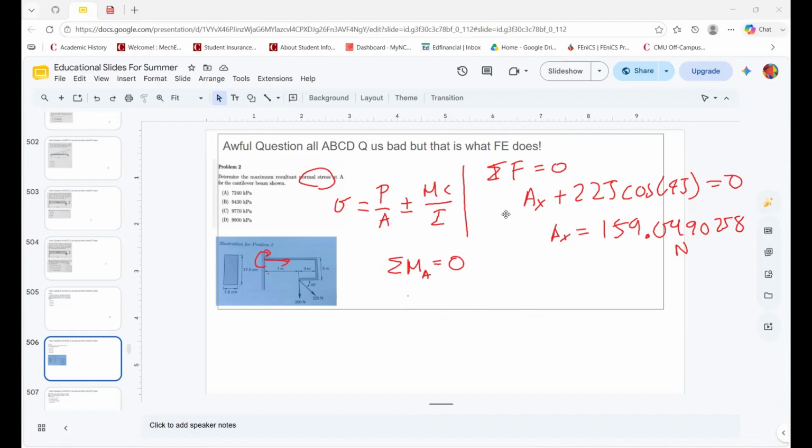The moment over here, we're going to do M at A, and we're going to choose a negative direction for it for now. And this was -2. Yep. But we could change it to positive or whatever, depending on how you want to do it. And it's plus or minus, so we just have to figure out the max so far. So then we have to do this one, which is going to be another minus 350 newtons multiplied by 7.